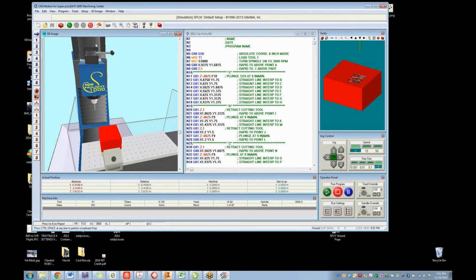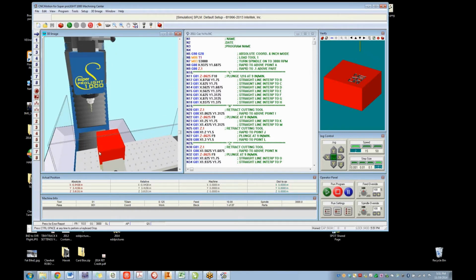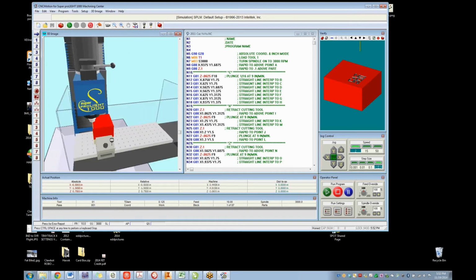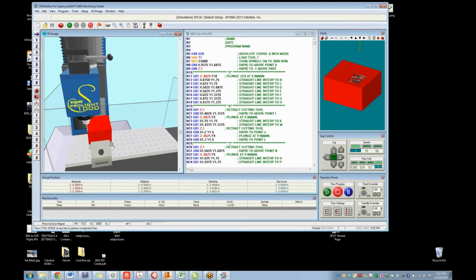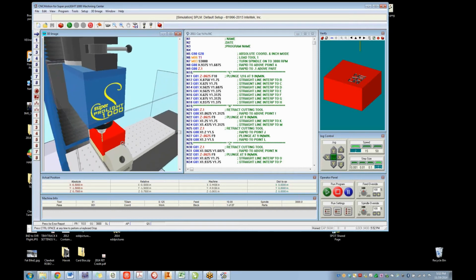Once that was all done, you have to literally drive your tool to the front corner, or whatever you called your part reference 0. In this case, I made the front left corner part reference 0. So I would have to drive it, and there's a neat little feature where I can send my tool to a corner by clicking on that icon, and it doesn't work like that in the real milling machine. You have to actually physically drive it there.